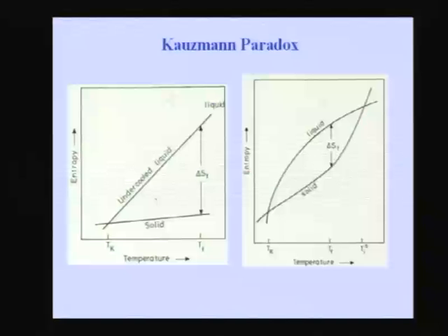There is also another interesting thing that happens if you take a solid and start heating it above the melting point. In fact, this is an experiment which a lot of people tried to do. Can we really heat a solid above the melting point without it becoming a liquid? It is a big question. We know that we can take a liquid, cool it rapidly, and when we cool it rapidly, we can make the liquid remain as liquid without getting crystallized at temperatures below the melting point.